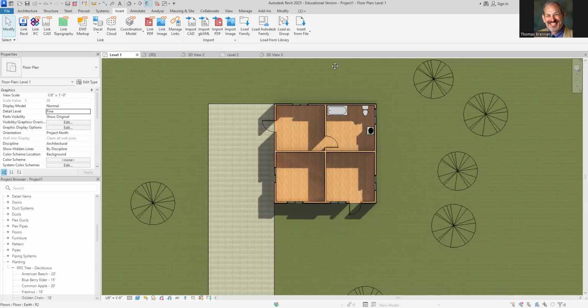Now, if you already have those, the problem is the actual height. So click on this, the edge of it, and then you want to change the height offset. Make it 0.5 inches, so that puts it up a little bit. Yes, there you go. That's it. Yeah, you got it.